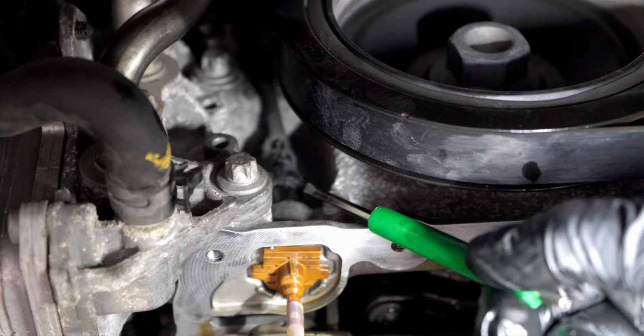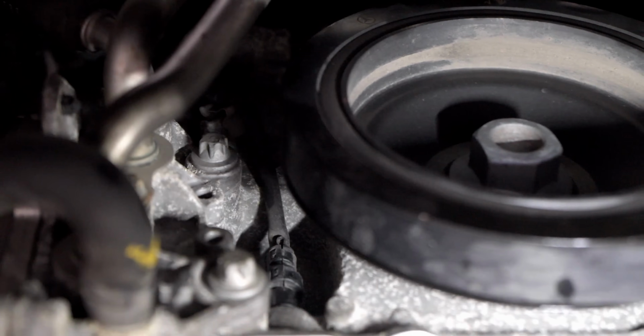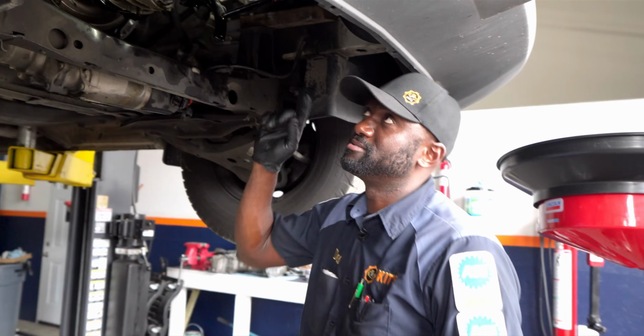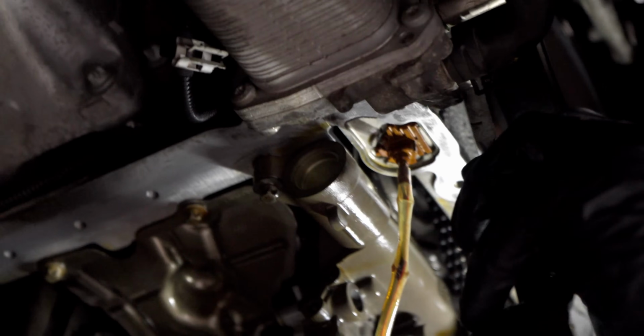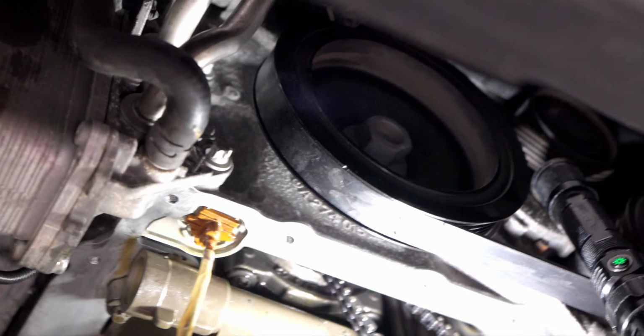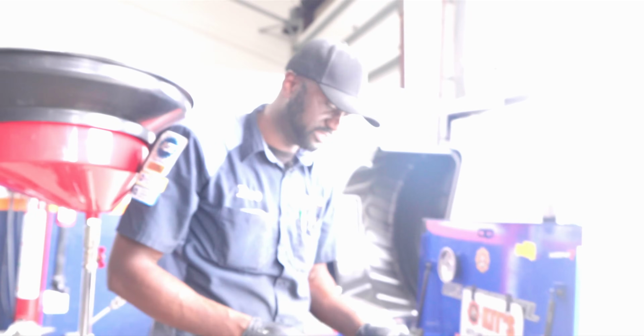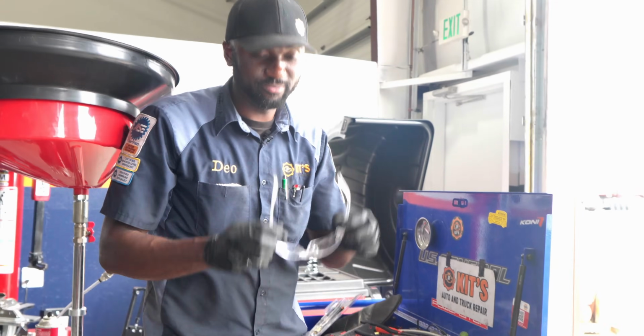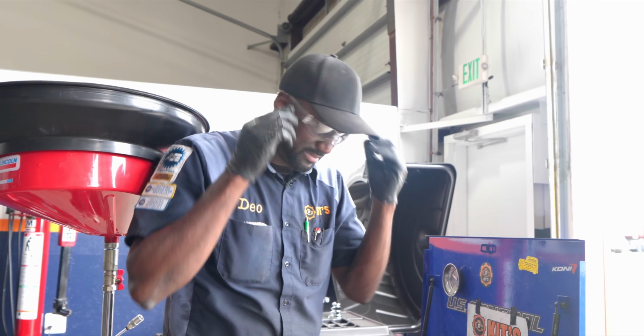See that electrical connector? Yeah, that's what I'm gonna disconnect. Now let's get this wiring harness removed. So I'm gonna disconnect the connector that I showed you up here. I'm gonna use these needle nose pliers. I'm gonna get to this little tab here. I'm gonna press it down and then pull up on the connector. Let me wear some glasses because those plastic pieces can fall and I don't want them to fall in my eyes.